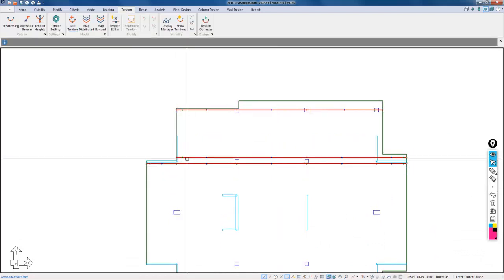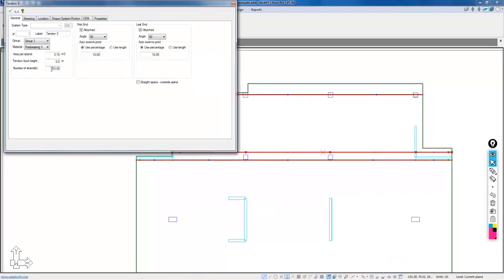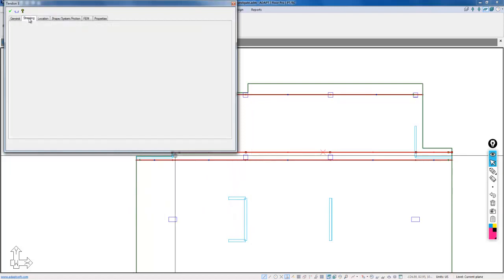So here I'm actually modeling 2 tendons that represent the total of 16. So we'll do 8 and 8. The reason I'm doing that, I like to just balance the force on either side of the frame line, and I have a dissimilar tendon. This tendon actually on the top cuts short because of this corner here and this tendon running out towards the wall. So we're going to use again the force of 26 kips.